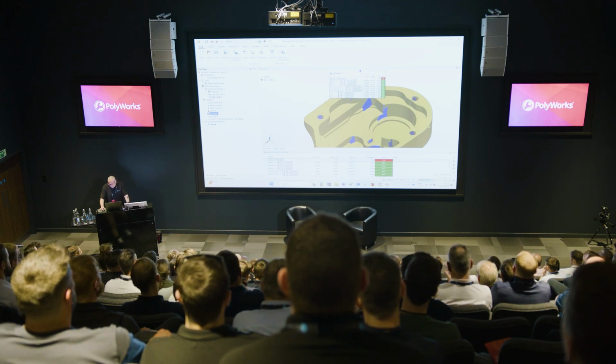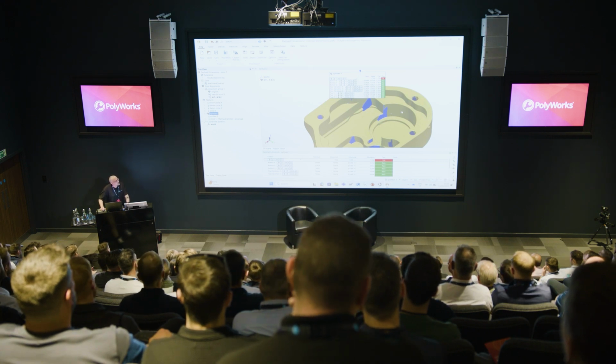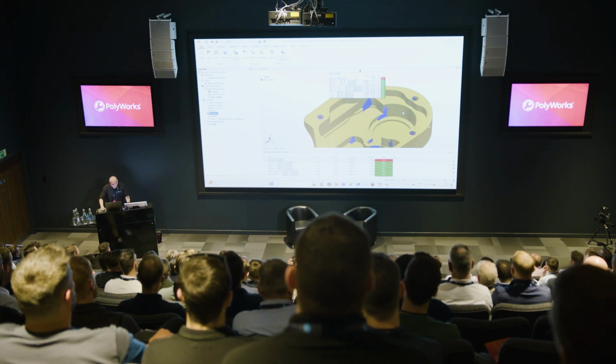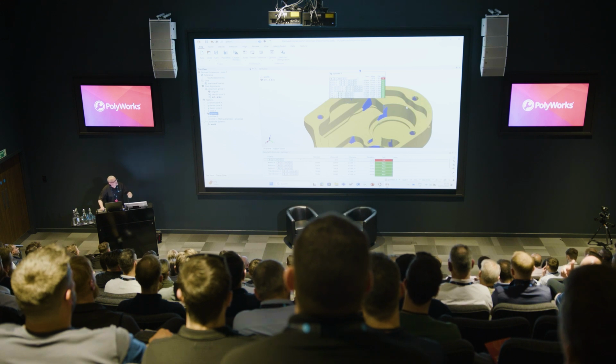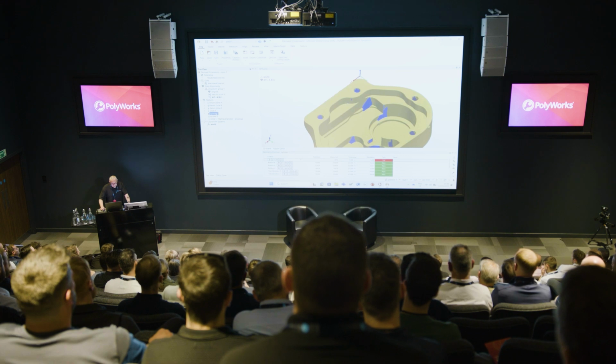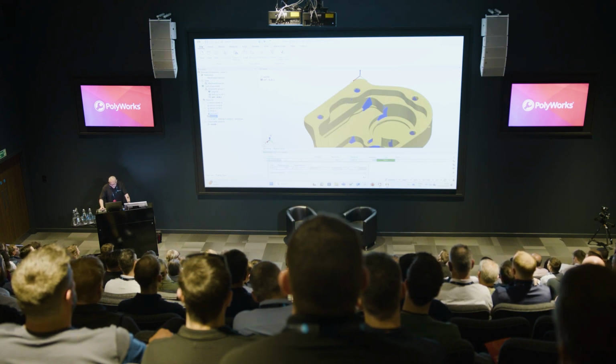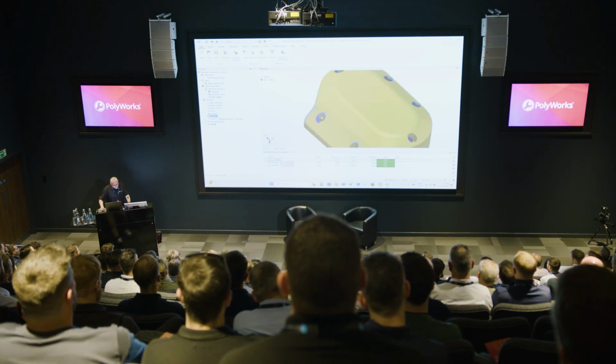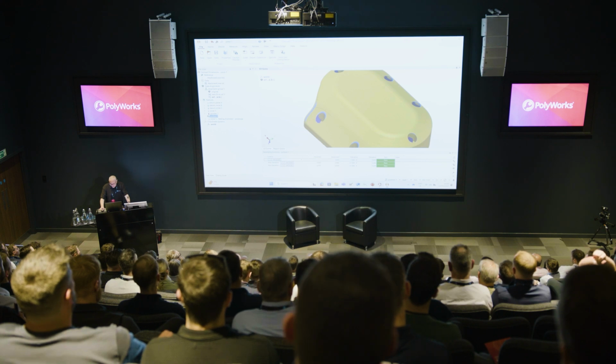If we go and change our GD&T standard to ISO, if you're working in ISO, the way it calculates the derived feature axis is different. So in that case, you'll only need to look at the maxes because it will never match your top or bottom. And then finally for the surface, we can go in there and add probably the min and max deviations, which are the most useful ones for a surface. Yep, so that's our derived dimensions.